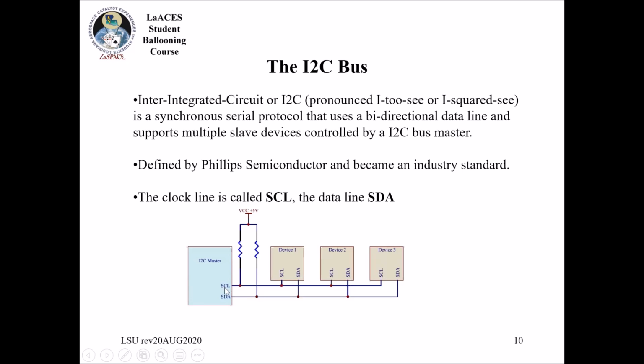And then also important here are these pull-up resistors. I have had a design before where we did not have these pull-up resistors. We thought we didn't need them because maybe a device says that it has a pull-up resistor. You definitely need these with I2C. So make sure you understand whenever you need to add them. Basically this is what's going to provide all of the lines being pulled up, and then each of these devices just has to sink the current to pull it to ground. That's basically what's happening. Okay.